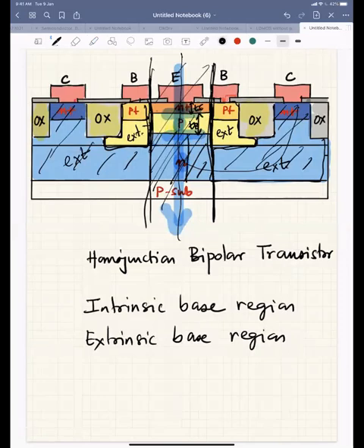And this is the thickness of my collector region, right? But in the books, this thickness, TE, TB and TC, we call it the width, right? Actually, in bipolar junction transistors current flows vertically, whereas in MOS transistors current flows laterally, right? So current flows from emitter, base, collector.